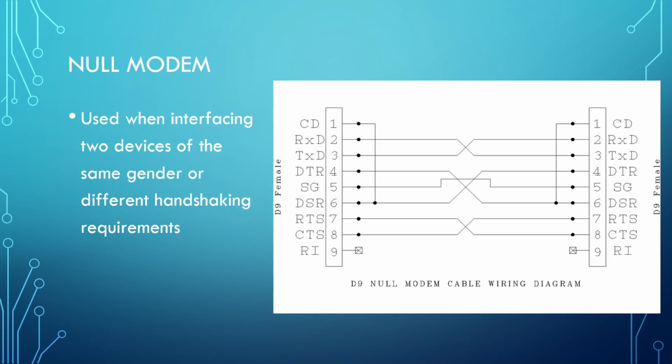All right. Null modems. Basically the whole point of a null modem, as you can see here, is that our RX and our TX data get flip-flopped, so those are important. Some other stuff gets flip-flopped too, our RTS and our CTS. But notice our CD gets pulled down to our DSR and things like that. The whole point here is basically to trick each other.